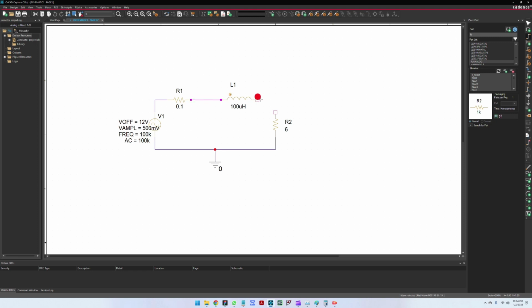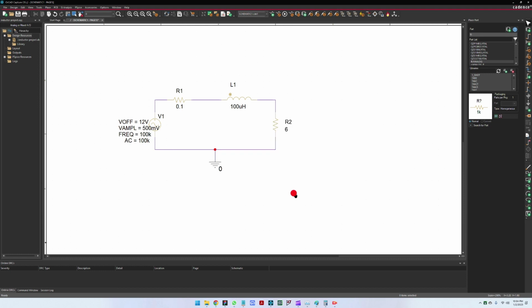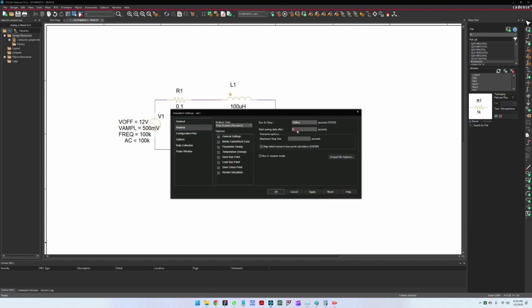Okay, and now we have connected everything. Great. Let's see how this circuit will run in a simulation. And for this, we have to create a simulation profile. On the top side, you'll see a new simulation profile button. Let's call our simulation Sim1. Click Enter, Create. And after we create the simulation, we need to edit the simulation profile.